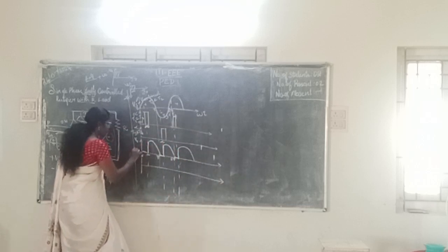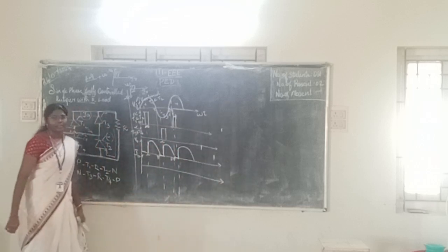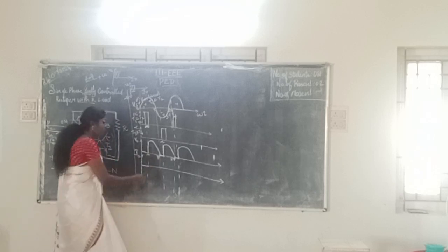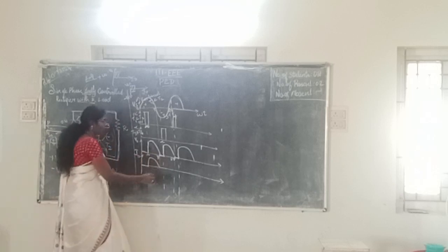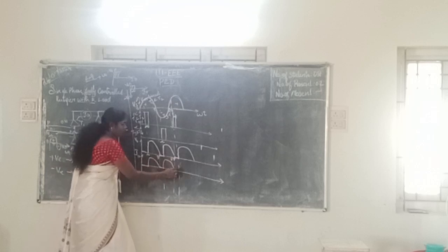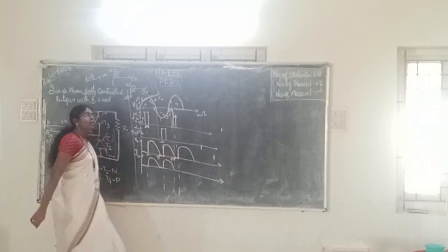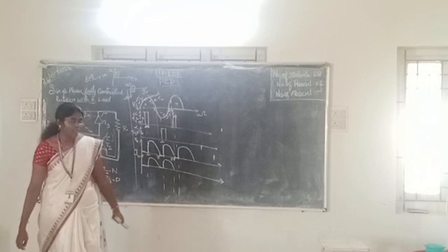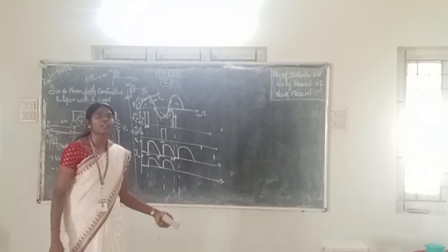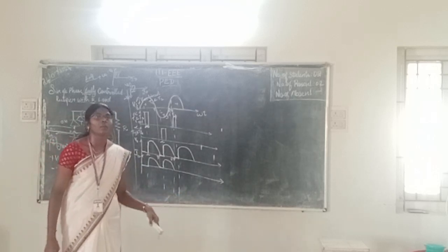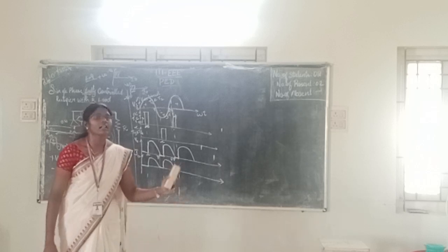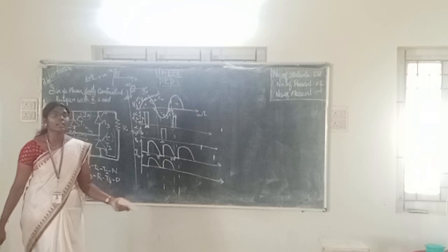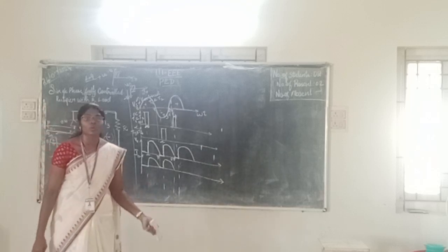The same for the output current. For an R load, the current remains 0 after the firing angle. In both the half controlled rectifier with R load and the fully controlled rectifier with R load, the output voltage and the output current will be in phase. As the voltage is, the same will be the current. The nature changes if there is any storage load.